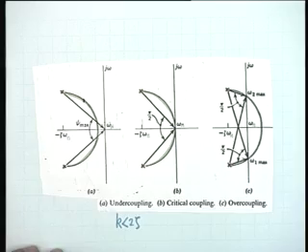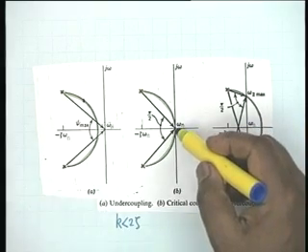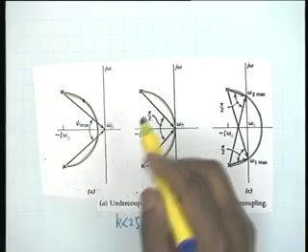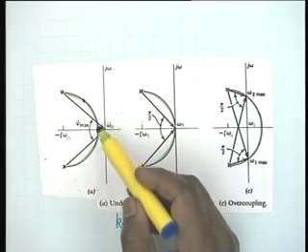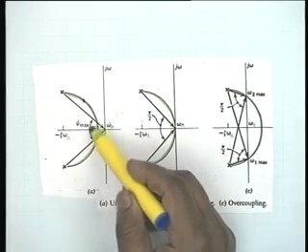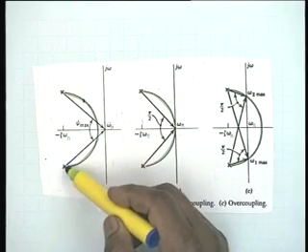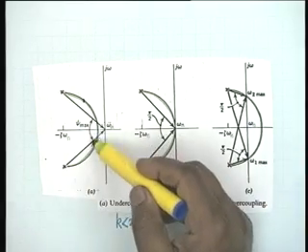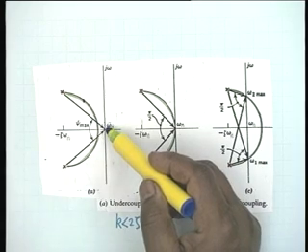Now the situation changes when the peaking circle just touches the j omega axis, and this touching must be at omega n. One more point: where is the maximum? You can easily show by geometric construction that the angle psi between the two vectors m1 and m2 is highest at omega equal to omega n.